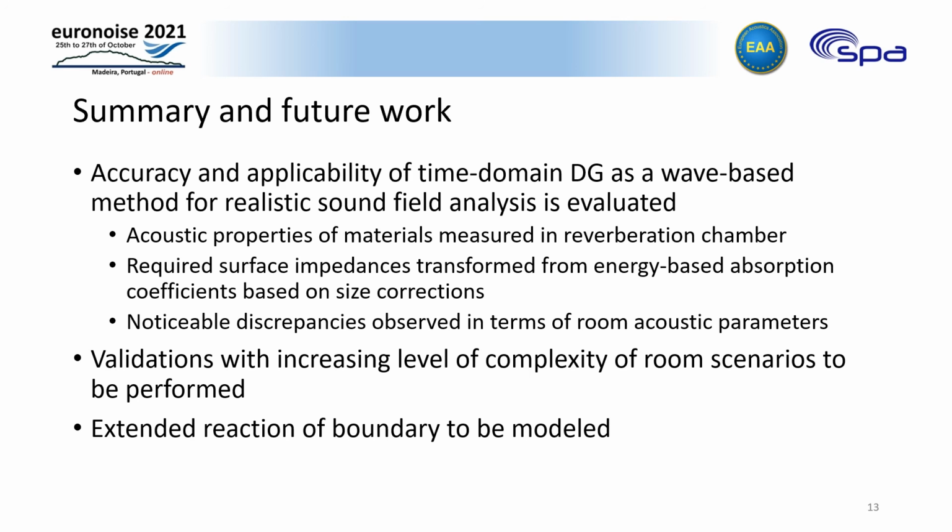Noticeable discrepancies between the simulation and measurement results are observed, especially for the reverberation time and early decay time. As for future work, experimental validations with increasing level of complexity of room scenarios will be performed. Furthermore, the formulation of extendedly reacting boundary conditions should help to achieve more satisfactory improvements in the simulation accuracy.